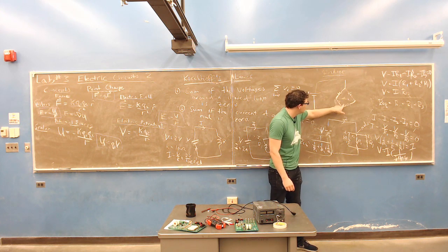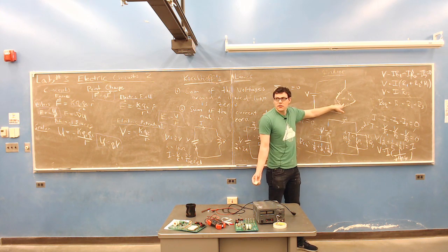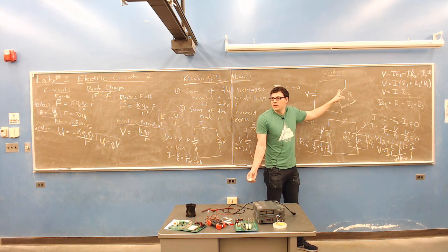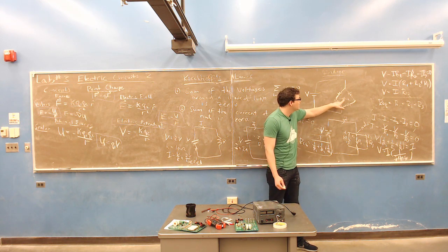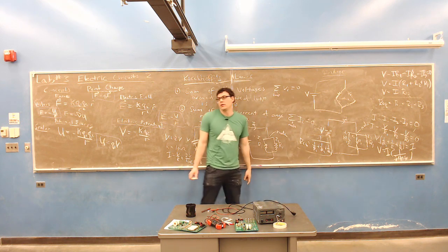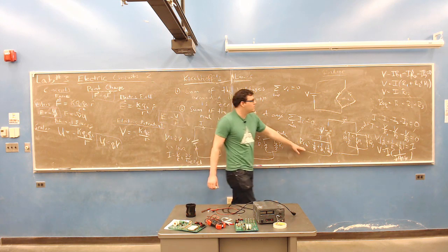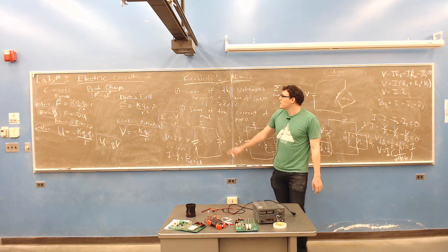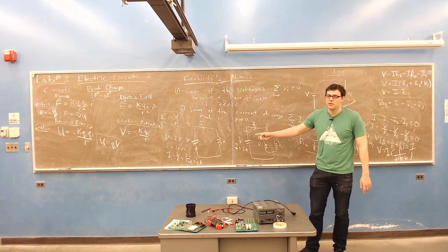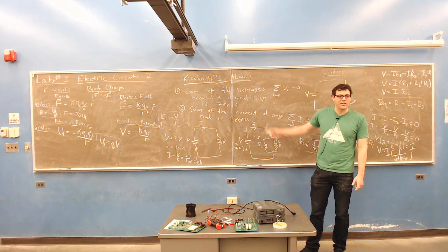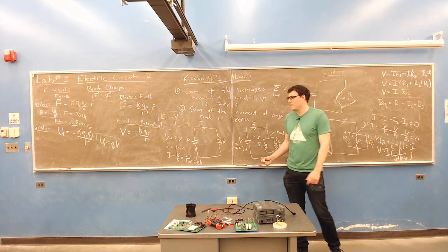Now, if I had a resistor across this part, it would be just parallels, right? A couple of series and parallels, and you can use a combination. And the fact that it goes this way makes it a non-trivial circuit. And that means we can't use these two laws, and the only way to analyze them is with Kirchhoff's laws.